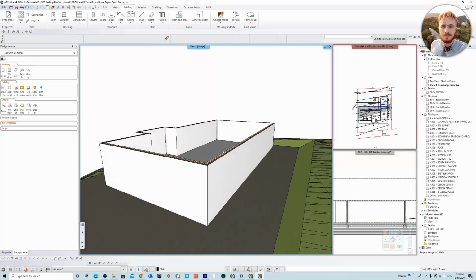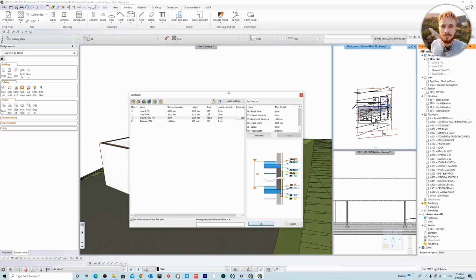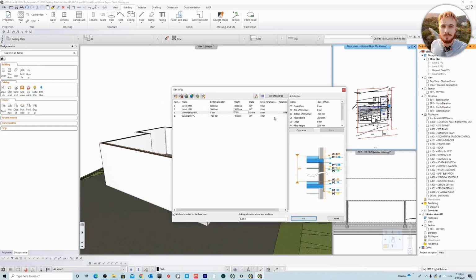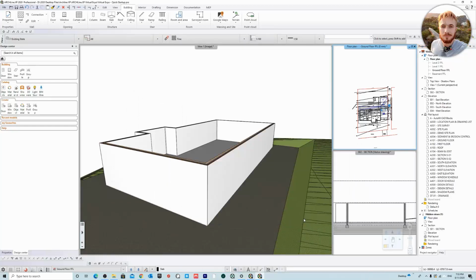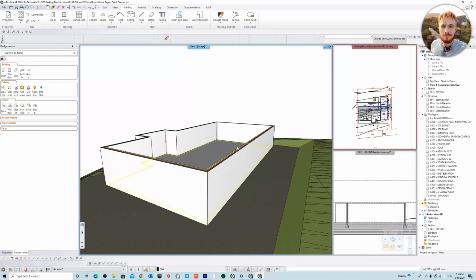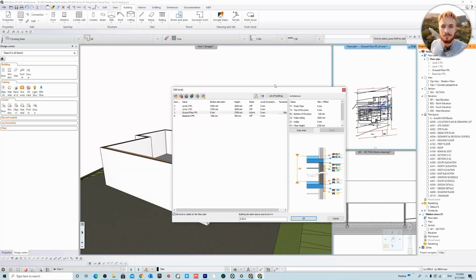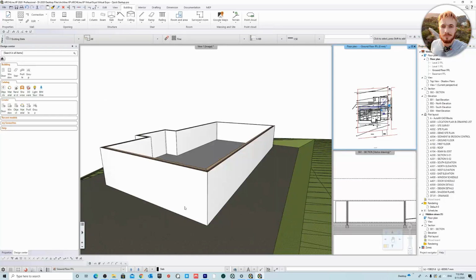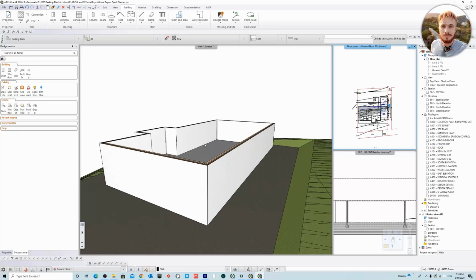and then the rest you just sort of fill in as your design changes. Okay, now the great thing about this, if I want to change all these wall heights, okay, I can just do it in one go. So I can just go to properties, okay, ground floor, let's say this changes to 2700. Okay, so I just change that. Okay, and then this updates all the walls. So you can see that's instantly updating everything at once. So this kind of makes it really easy to work with different consultants, and if there's something that changes, you can just update this once into your design. So let's go and update this. Just hit rebuild, and that's going to update everything.